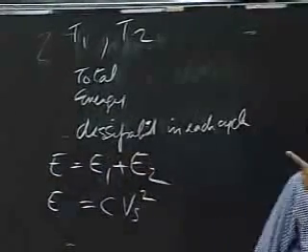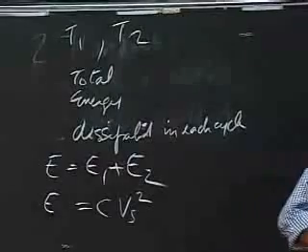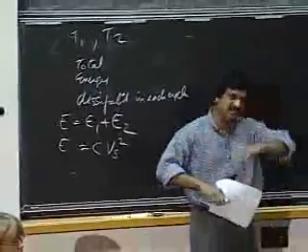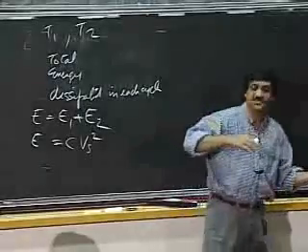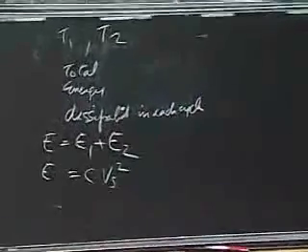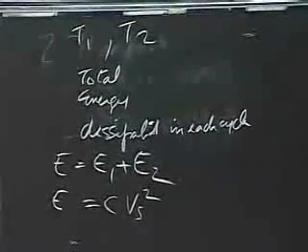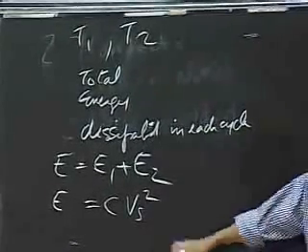So if I have an arrangement of switches and capacitors like that, I charge the capacitor, discharge the capacitor, charge the capacitor, discharge the capacitor. What it's saying is that in a charge-discharge cycle, I'm using up C Vs squared of energy: half C Vs squared when I charge it up, and half C Vs squared when I discharge it. That's what I get.